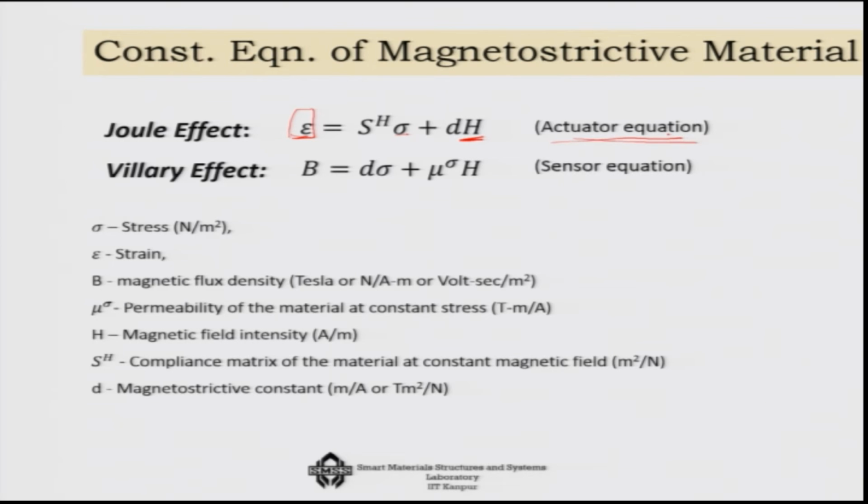Similarly, if I apply a stress and see a change in magnetization, not through the application of a magnetic field but through the application of stress, then that is known as the Villari effect. And these 2 equations look very similar to their counterparts for piezoelectric materials.